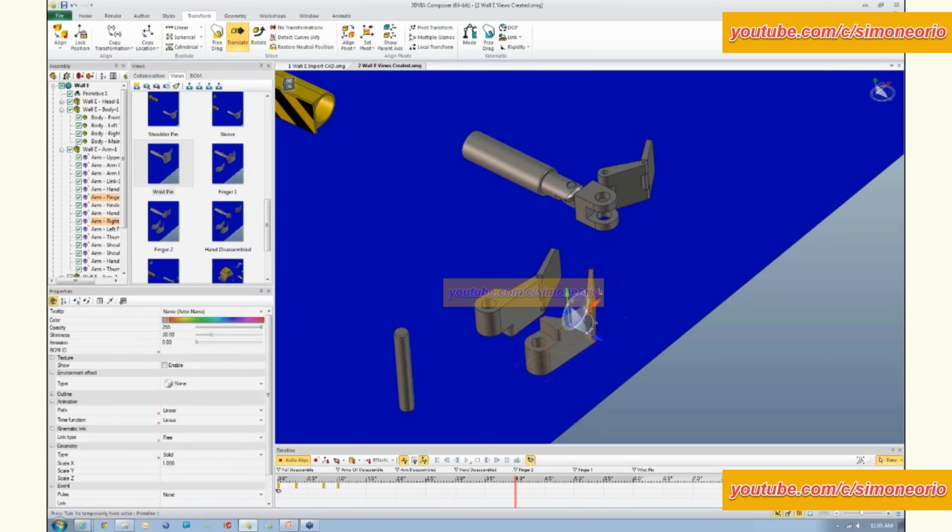So we make our selections, we've got our filters on, still on. So now the keys down here are representing only the location keys for the actors that I have selected. And if I grab my time bar and slide it back and forth, you'll see the motion now being described.